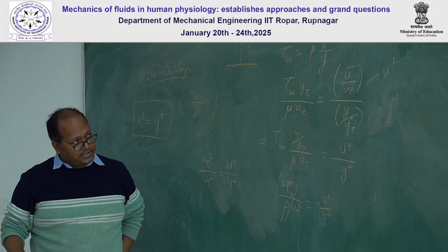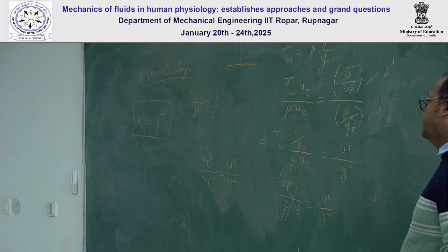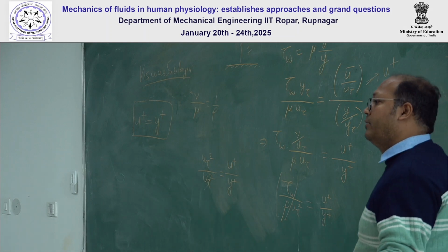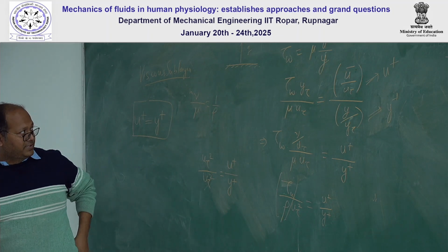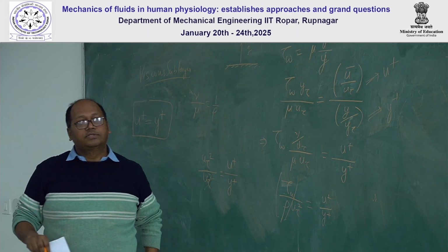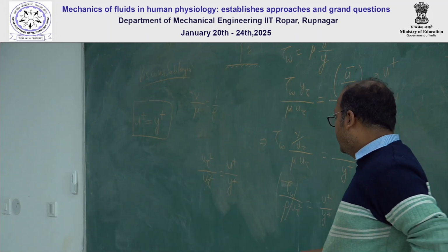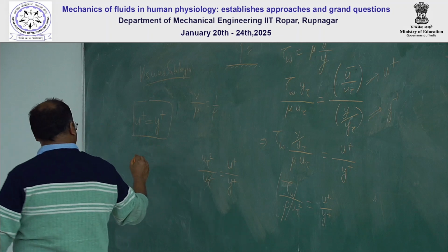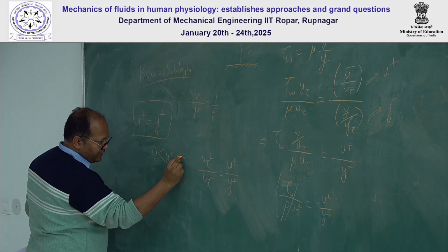Many times people, without going into the intricacy of k epsilon, k omega or k SST omega, at least my students from Nath earlier, he always used to say that it is always better to use the k SST omega model for wall bounded flows, because this region is from 0 to 5.